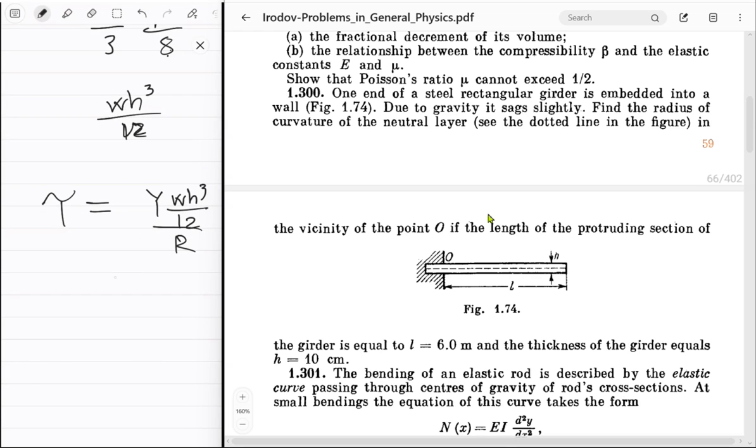Now we will have to figure out what the torque is about this point, of this complete system. So this is the total mass of this guy. So the mg force acts at L upon 2, so it's just mg L upon 2. That's our torque about that point, right? Yes, I think that's correct.